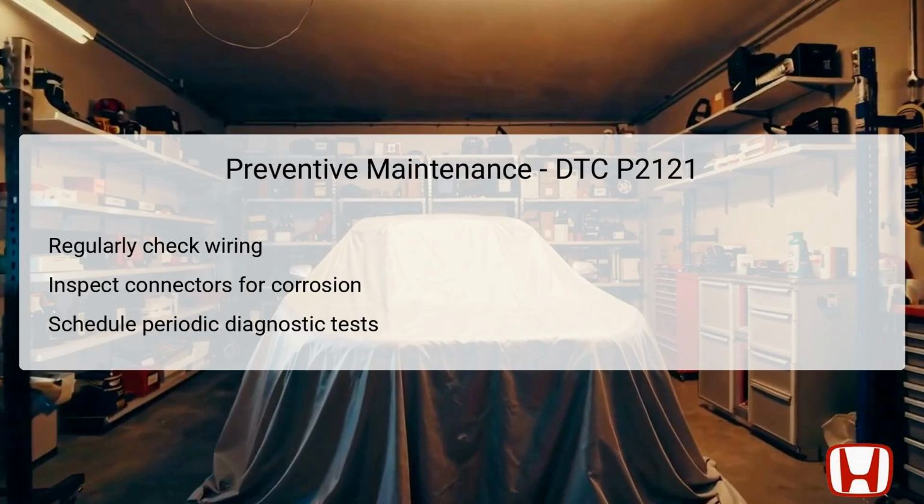Preventive maintenance is crucial not just for DTC P2121, but for overall vehicle health. Regularly checking the wiring associated with the accelerator pedal position sensor is essential to detect any signs of wear, fraying, or damage before they lead to bigger issues.